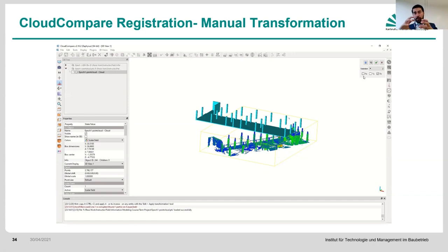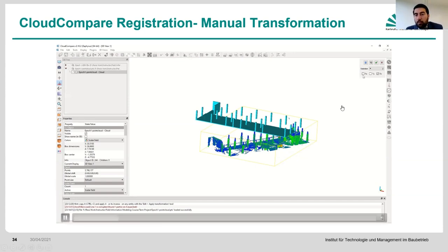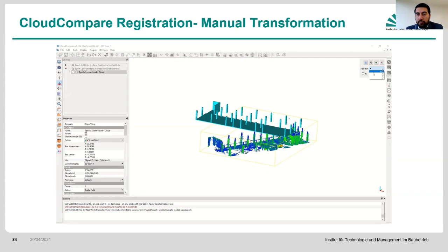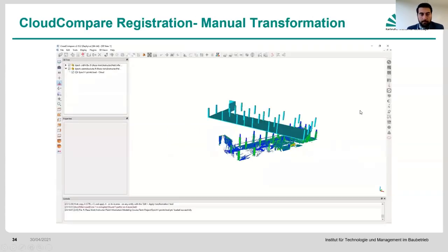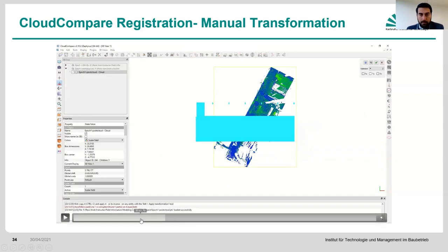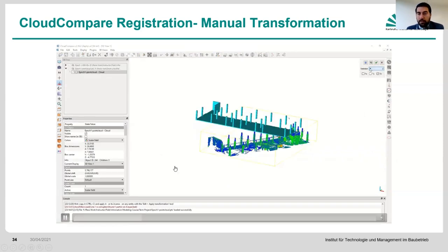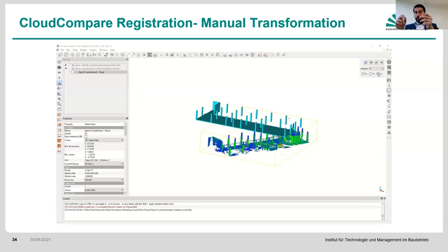This does not have any orientation, meaning your model does not move or rotate. What it does is only translates. The second part up there is the rotation, which if you click on the rotation there, you're going to see XYZ, which is basically your particular orientation overall. And then you can actually select a particular orientation and rotation axis. Meaning if you have the Z axis as your orientation, your model would only rotate about that axis.